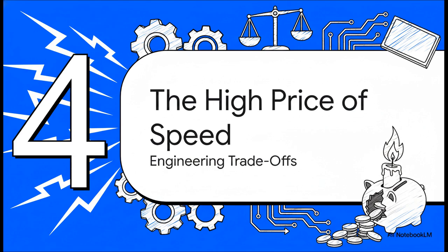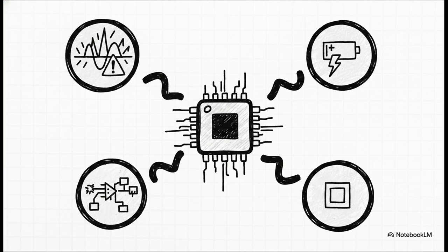ECL's blazing speed comes at a price, and it is our job to understand what those trade-offs are. And here they are. ECL circuits are power hogs. They can't drive a lot of other gates. That's what we call low fan-out. And those negative voltage levels mean they don't play nice with other logic families.